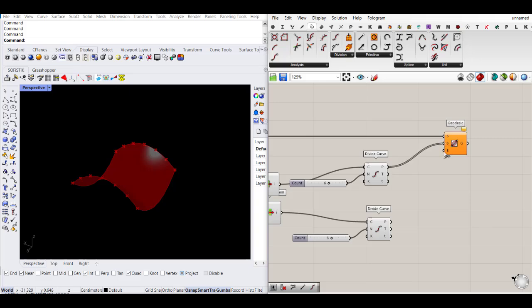And now if we connect both of them together, you would see that the first point from this curve would connect to the first point of the other curve, which is here, because the direction of these 2 curves do not match. To solve this, we need to either flip this curve from beginning or just do a reverse of the points, which means we change sequence.